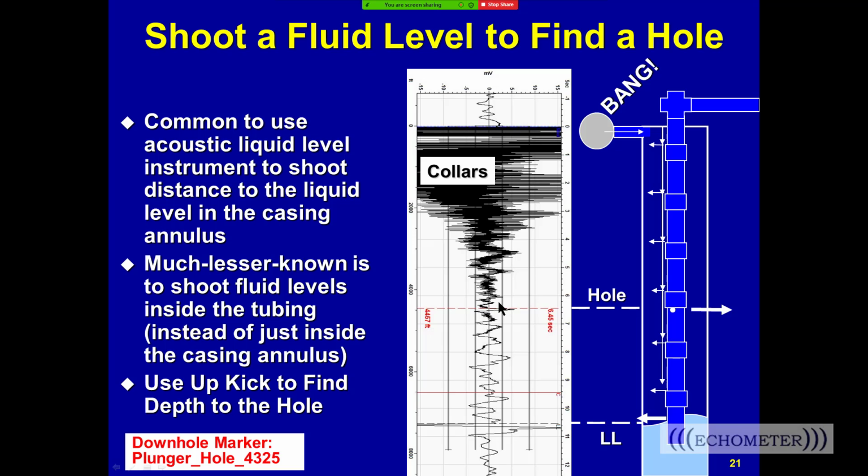And we just got a question, I'm going to bring it in because it's related to holes. Hamdi from Tunisia is asking if the hole matches a collar, can it be detected? Well, if the hole is a hole, the answer is yes, because you'll see an upkick at the collar. But if the hole is just a leak through the threads, then the answer is no.